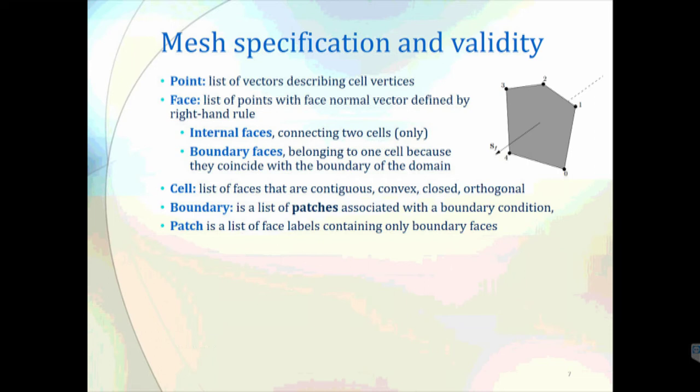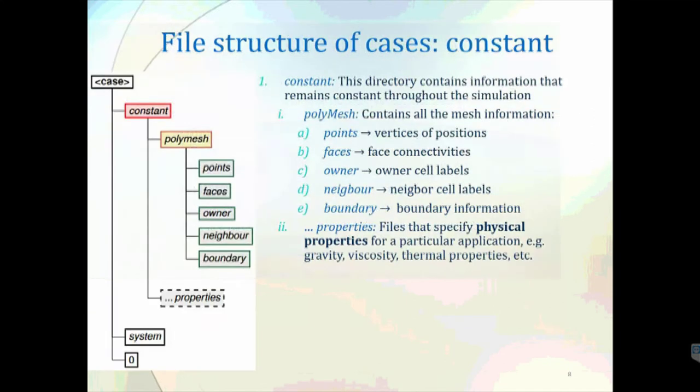So finally, we have the list of the cells, the definition of the cell, and a definition of boundary. Boundary in OpenFOAM is simply described by a list of patches, or a collection of faces. So we can just define in OpenFOAM which faces are representing our boundary. Of course, this will be more clear to you when we are discussing an example.